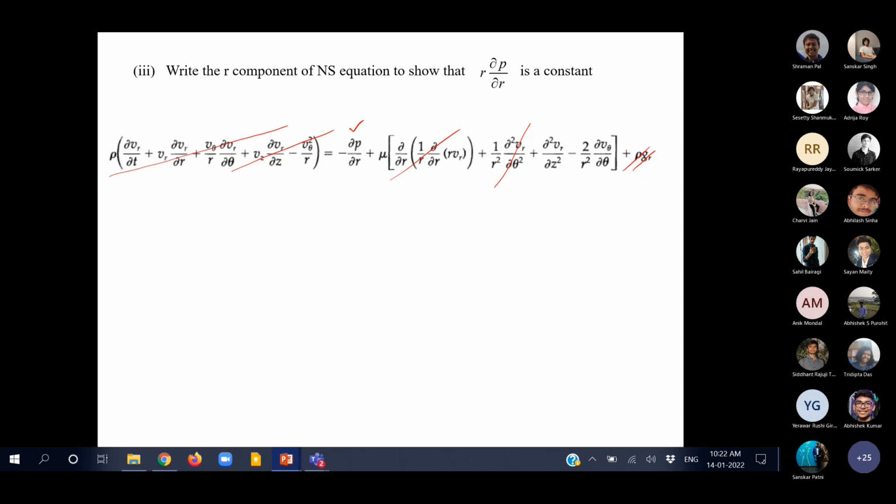Non-zero, because VR is a very strong function of Z. It's 0 at some point, and some velocity at a location not far from the original location. So the gap is small, so there is definitely a large velocity gradient present in the system. And if there is a large velocity gradient present in the system, then the viscous transport of momentum in that direction at least would be substantial and cannot therefore be neglected.